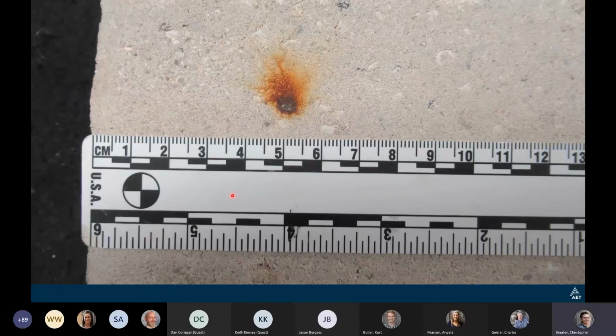All right, here's another good one. This is a concrete paver, and our client wanted to know what caused that iron stain. And you can see that right in the center, that black, that's the actual particle that's remaining. And that particle is a sand particle. It's probably about 2 millimeters. So that's right around a number 8 sieve. And being that small, look at the volume of the stain it produced. You know, that's a large noticeable stain, which is why it was sent to us.